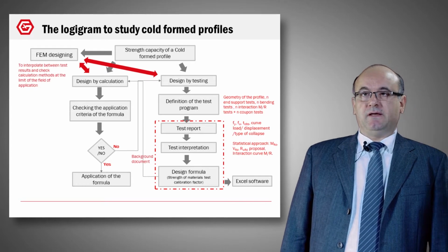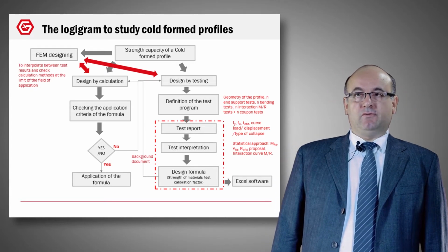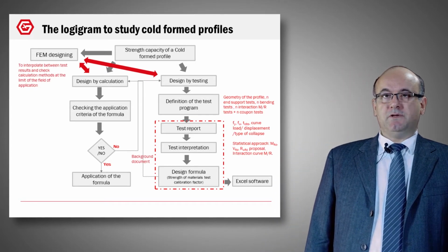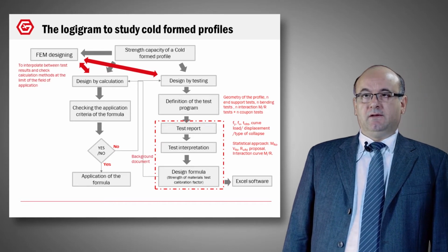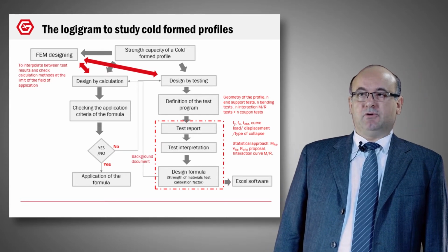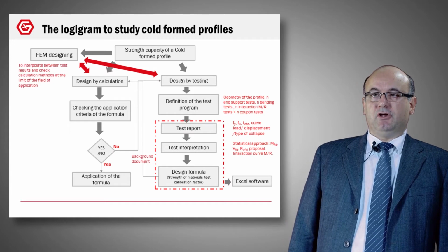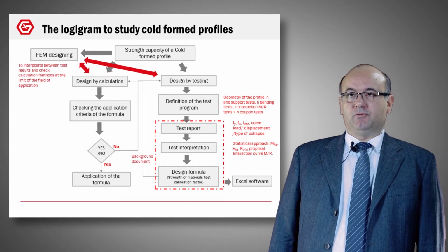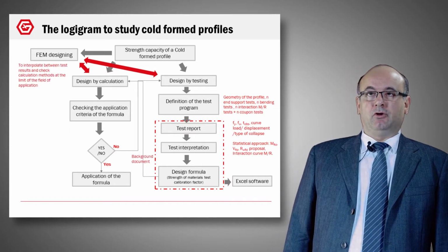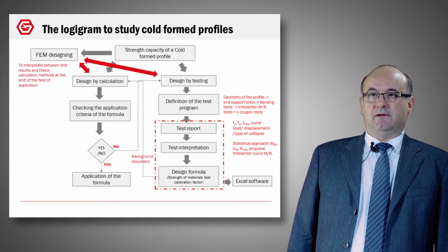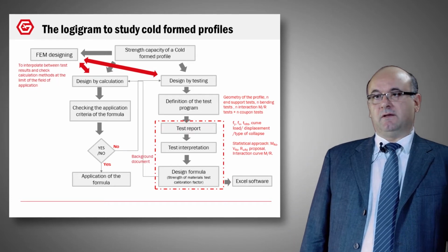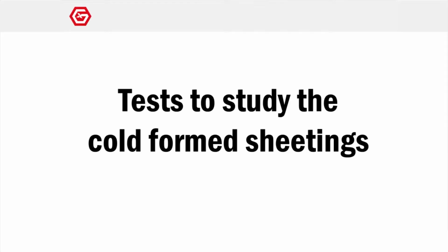Now it remains the FEM designing. It's difficult to use because cold-formed elements are very sensitive to local buckling. But it's very useful to make interpolation between tests, or to develop new tests or new profiles, to avoid too large a number of tests. And what is done after, you can again make design by testing and design by calculation. Okay, now we are going into detail on the test program and the design by testing approach.